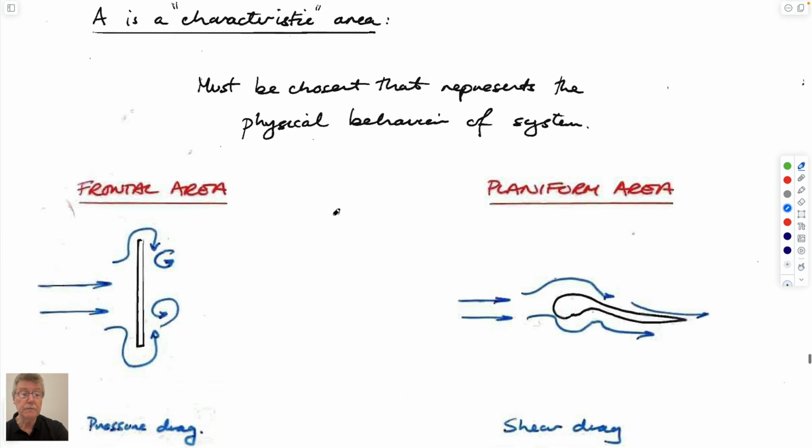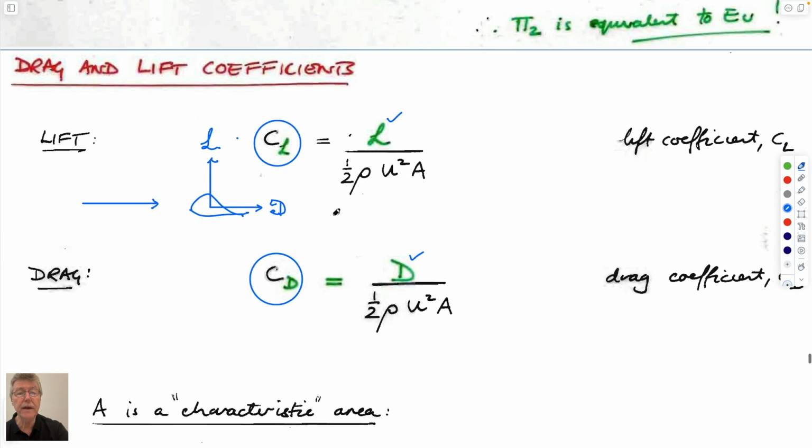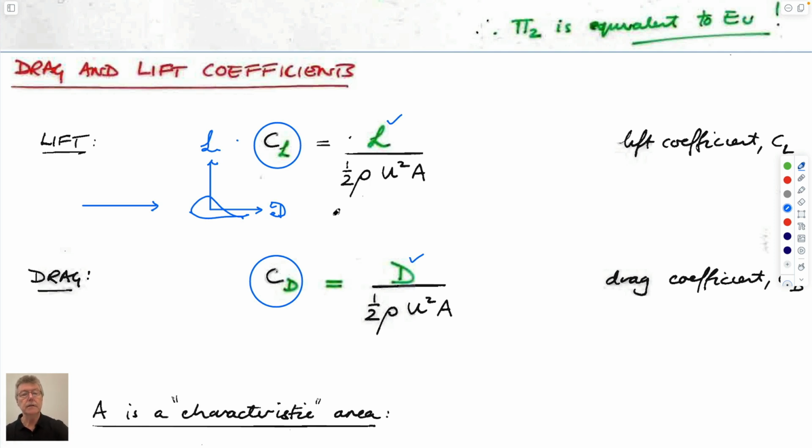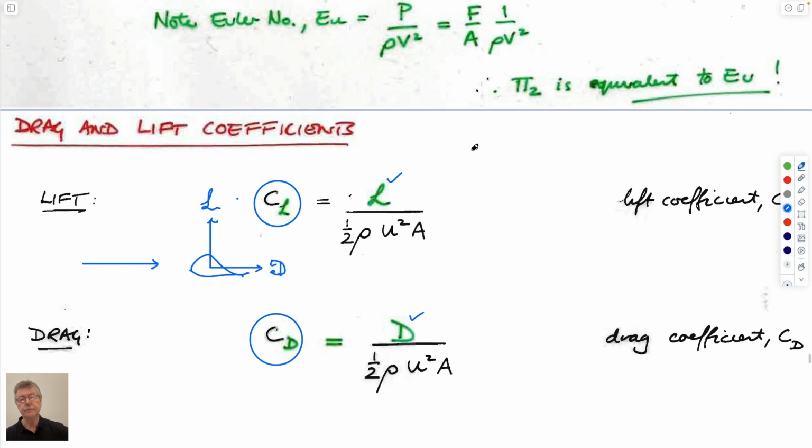So lift and drag coefficients. And so these would automatically, I guess I can draw that, include the two components we talked about. So if this is the coefficient of drag, which is also really just an Euler number, and this is the Reynolds number, then we know from what we just looked at that this is our behavior, right?